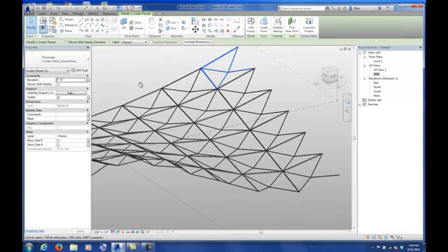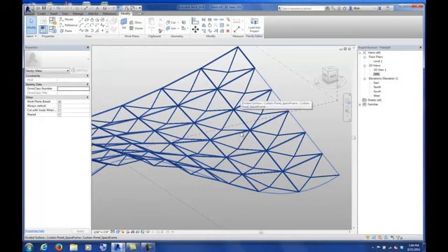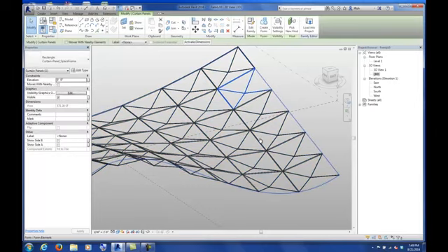And if I look to the left, I see my show side A and my show side B parameters. And I have no idea which one's A or B, so I'm going to pick one. And that wasn't the right one, so I'm going to go to B. And you see how that appears? I'm going to do that to all of my ends. And I could do this in multiple fashion by tabbing over, holding the control key, and so on and so forth.